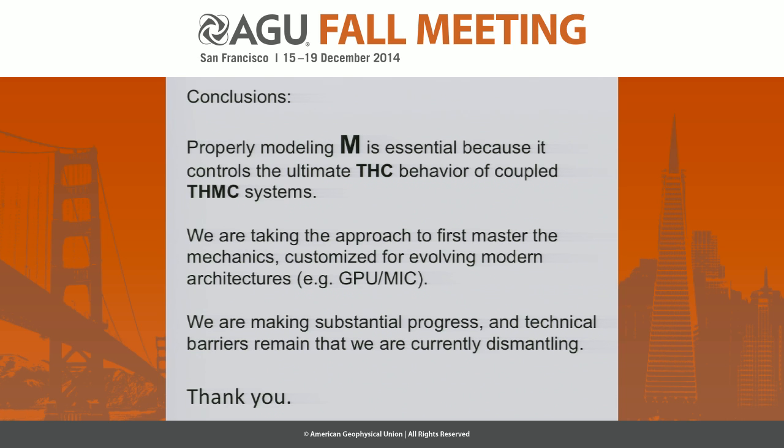And please speak up. I don't hear very well. Hello. At the permeability test, it's expressed in terms of sigma bar. What was exactly the sigma bar? It's the effective normal stress. Okay. So basically, if you have a high normal stress, you have low permeability, and it's a proxy for the aperture. I thought it was kind of average. No. It's the effective normal stress.